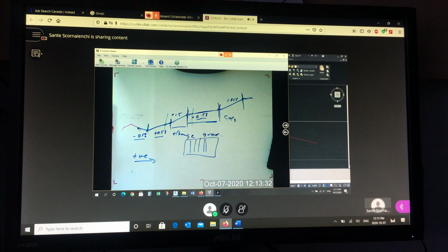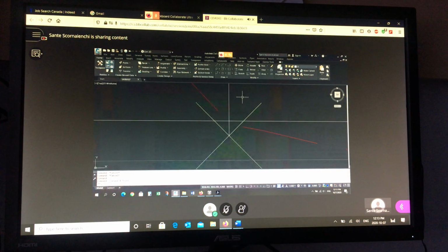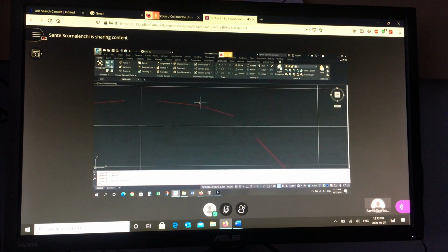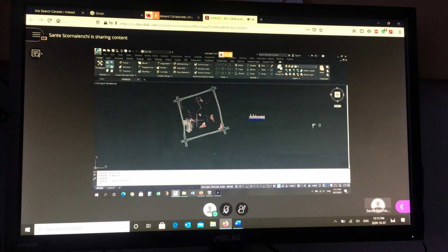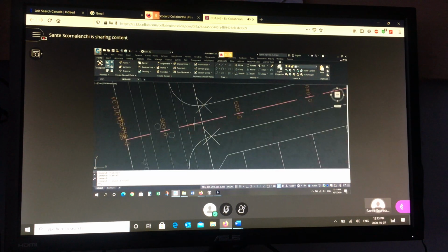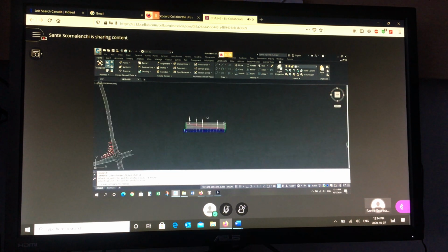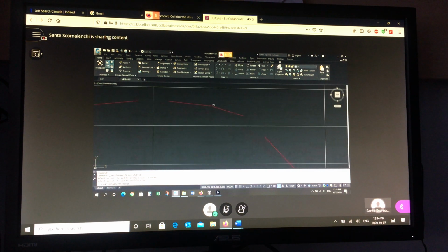And then I need the edge of asphalt here. You can either get it from the profile, it's right there, or you can project it. You can actually put a point on center, a point at the intersection of the edge of asphalt and the center line. That's my first design elevation to match existing. Project that point, and it shouldn't be a surprise that it falls exactly here.